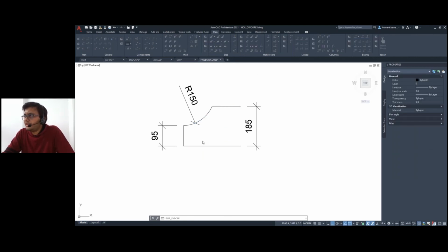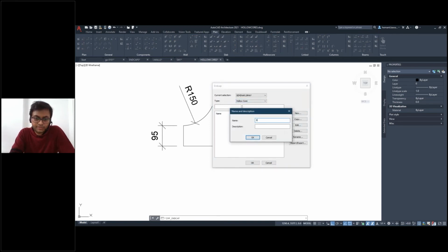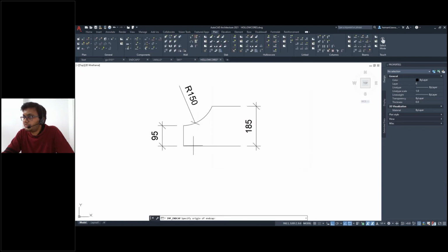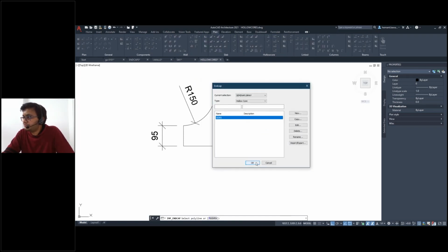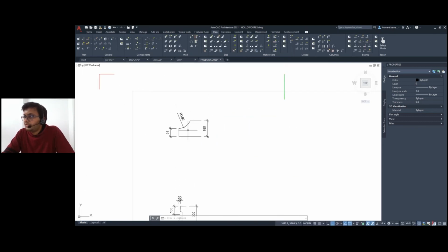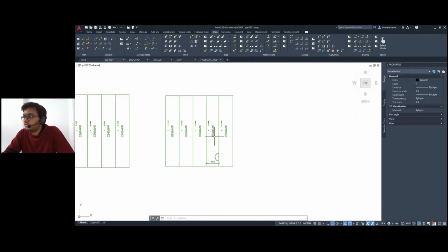So we'll go into the end caps, again hollow core, new one, sides. Okay, we already have the level 1, level 2. We'll select the geometry, we'll select this, yeah, okay. Now the thickness of this one is 185, and let's see what we have for this one.